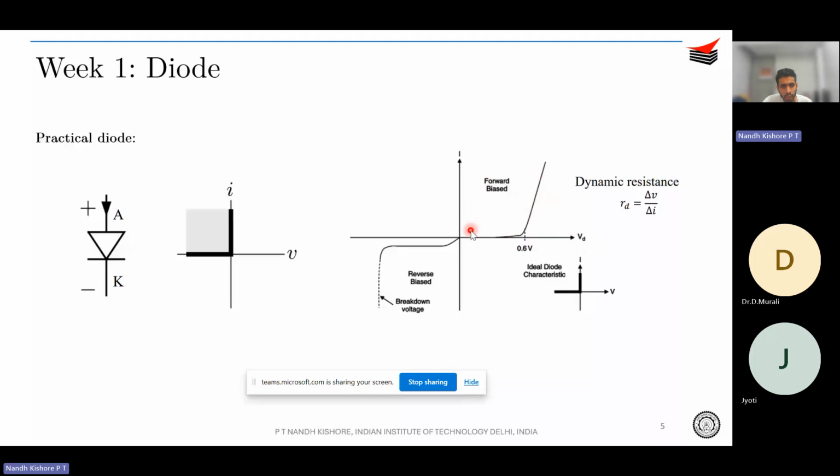And it is also not that the diode can continuously withstand the negative voltage, or the voltage between cathode to anode. So if we do apply voltage between cathode to anode, there will be some reverse current that would flow, obviously, right, between cathode to anode. But beyond a particular point, beyond the rating, the diode would undergo an avalanche breakdown. So that is known as a breakdown voltage, or the diode gets damaged and a huge current would flow through that. So that is what signifies the almost